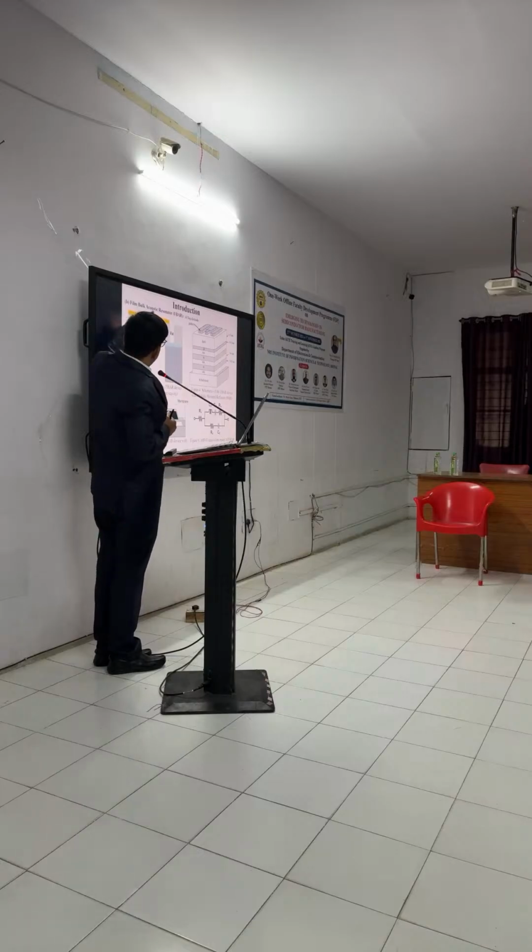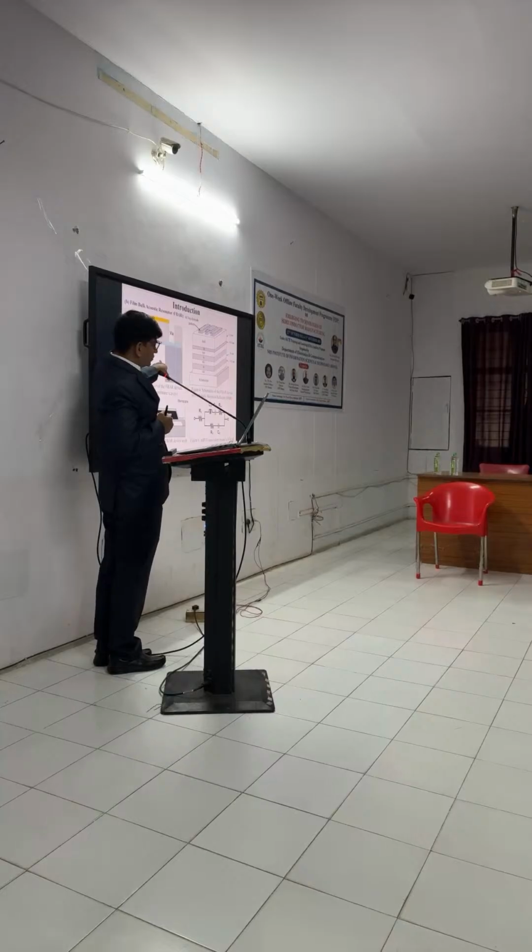Once this acoustic signal travels back and forth, on the top side it will be reflected because of air, and on the bottom side I also have an air cavity. So it easily travels back and forth between the top electrode and the bottom electrode. Once you have done this, you can design your resonator. Now you have a resonator in your hand.